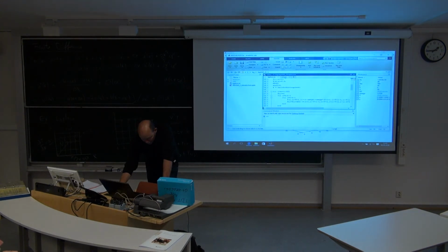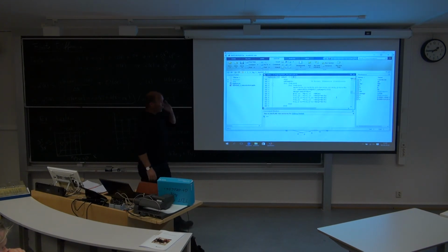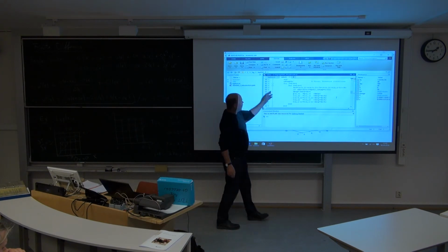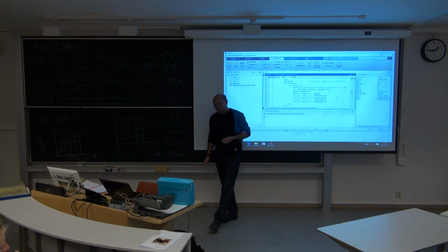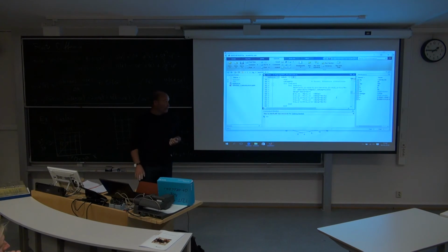if we now jump back to this SOLA algorithm, where we haven't gone through every detail yet, it will be more next time, but here we actually have an SOR iteration, updating the pressure and the velocities. And this is actually an SOR, successive over relaxation, with a fairly okay omega.